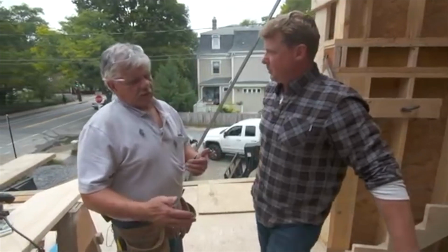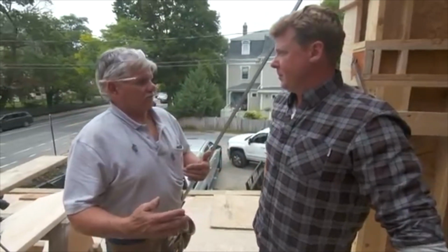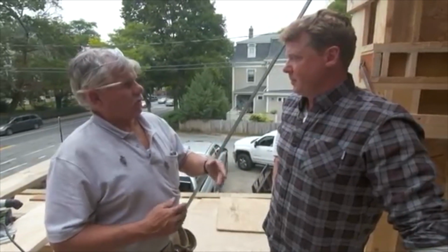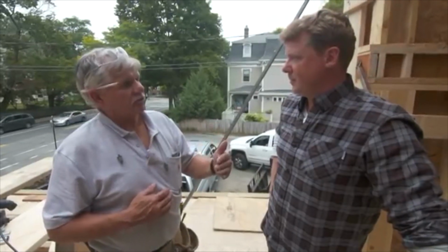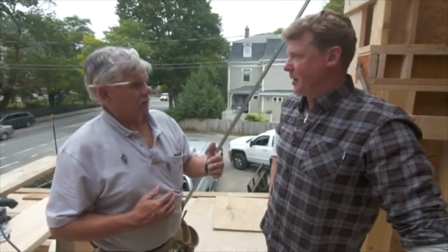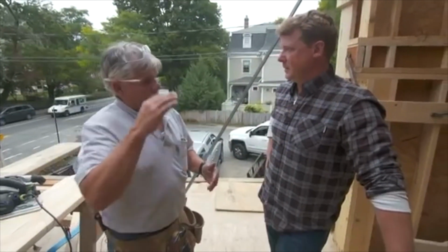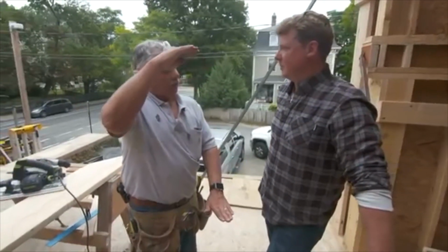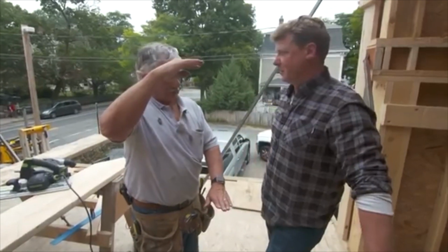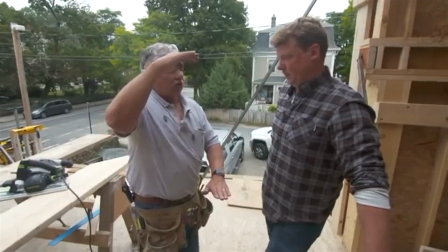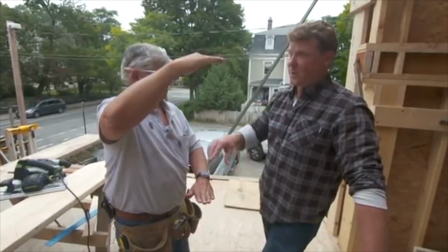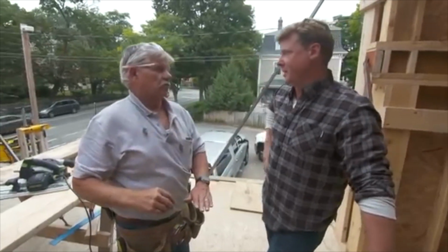Well, you figure that's an average of about 10 inches, 10.5. So if you take 2 steps on a riser, you want to be around 26 to 27 inches, which is the right number to be at. But when you're figuring out stairs, you have to calculate the height from point A to point B, first floor to second floor, for example. You have to think about what finishes are going to be on this floor and what finishes are going to be on that floor. Hardwoods here that are 3/4 of an inch, tile there that's half an inch.